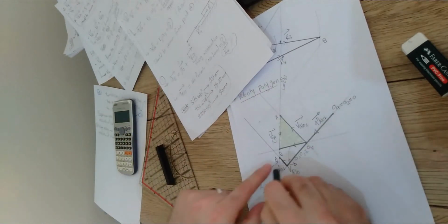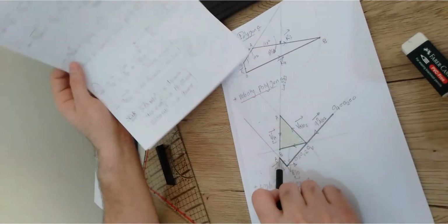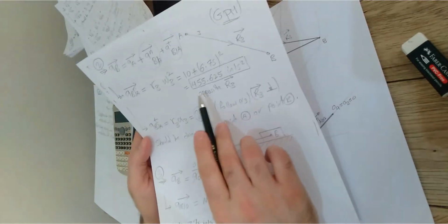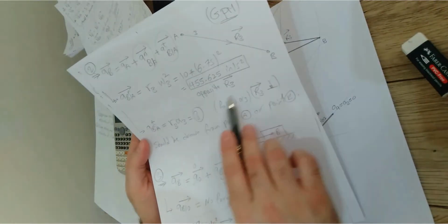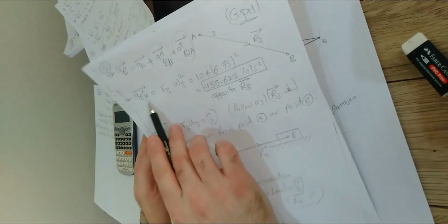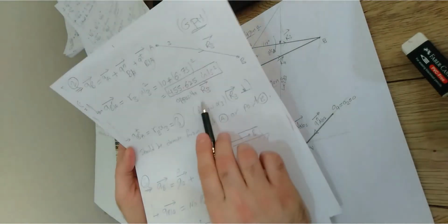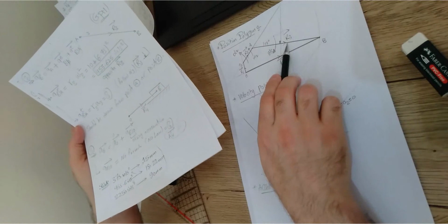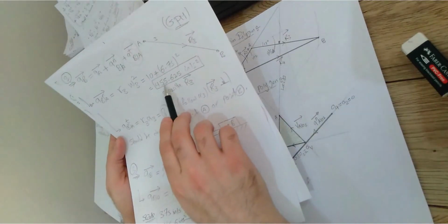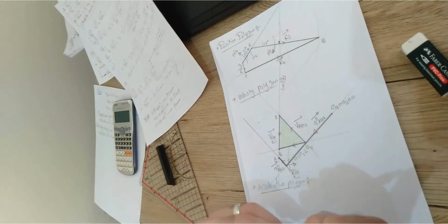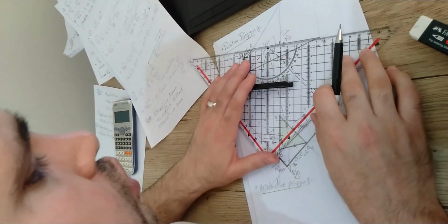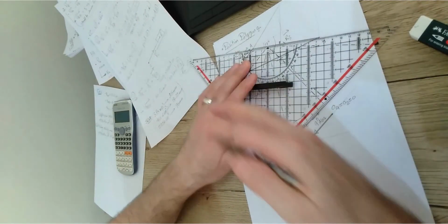So this is the normal and tangential. We got point A here. Now we're going to draw the normal component. The normal component should be in the opposite direction. It should be drawn from point A, since we have point A, opposite to the R3. So this is the R3 direction, right? And with this value, right? So let us first draw a line that is opposite to the R3. This is the R3, so I need to draw a line that is parallel to R3 and go opposite.